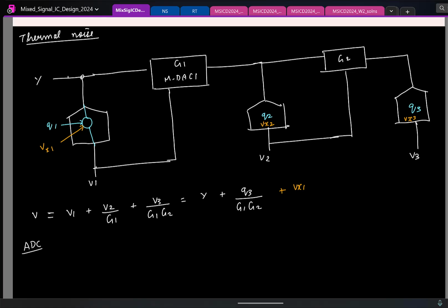It is adding along with the quantization noise. So how is it going to appear at the output? Why? What he's saying is the simplest thing. I know that if you have quantization noise here, does it appear at the output? So if you add anything along with the quantization noise, will it appear? It's the same point that this is getting added. So anything you add along with the quantization noise is not going to appear at the output. So nothing from the first ADC will come.